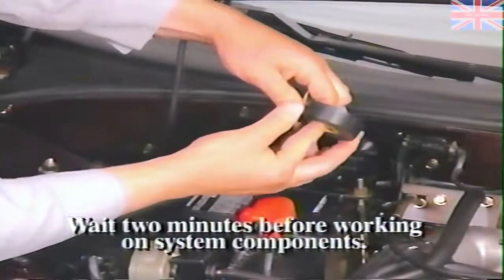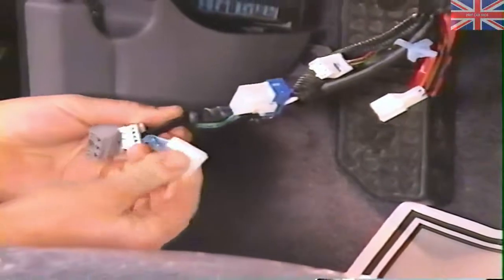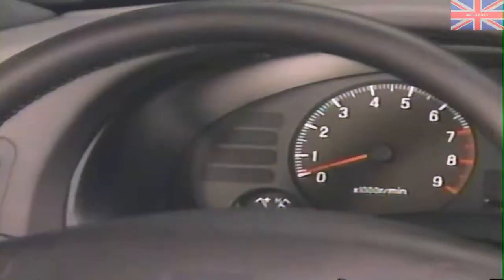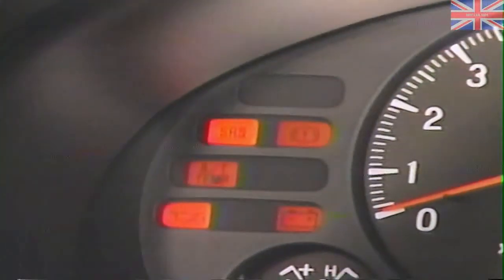Then wait 2 minutes for the system capacitors to discharge. Front impact sensors, the SRS diagnostic unit, clock spring, and airbag modules are each serviced as an assembly. Do not attempt to repair any of these components. In addition, if a wiring harness connector is damaged, replace the appropriate wiring harness. Before baking the vehicle after painting, remove the front impact sensors, SRS diagnostic unit, airbag modules, and clock spring. And after servicing the system, check the warning light to make sure the system is functioning properly.